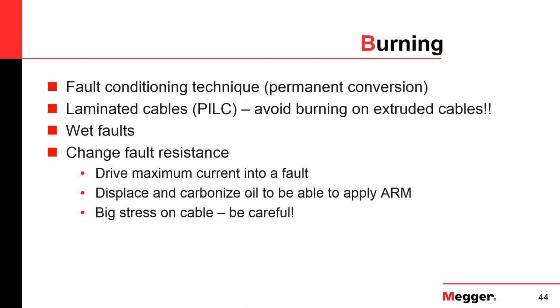On plastic cables, it is really your last stand, because it can actually really harm your cable. It will heat up your cable, and a large amount of current for a long amount of time can actually melt the insulation at a certain point, and then your concentric is actually trying to slowly wander towards the conductor.